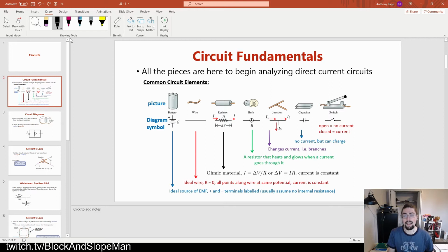If that is not on the drawing, that's okay. Look for the longer line. The longer line up top tells you which side is positive. Wires are just shown as straight black lines, nothing crazy about them. Resistors are squiggly black lines, right? Or zigzag. A light bulb is sometimes just drawn as a resistor because it is a resistor.